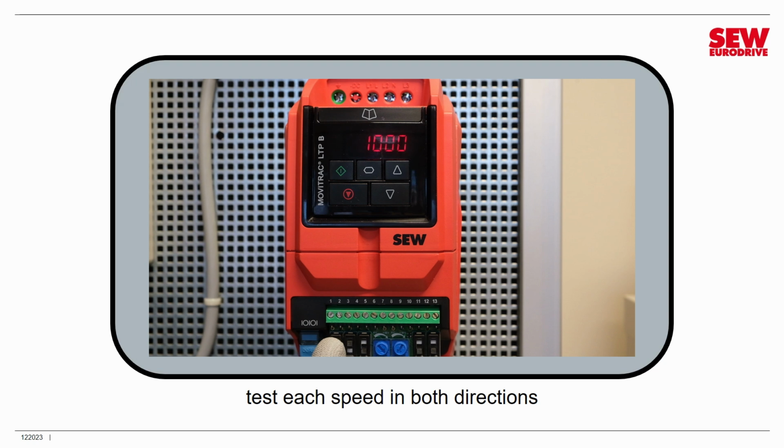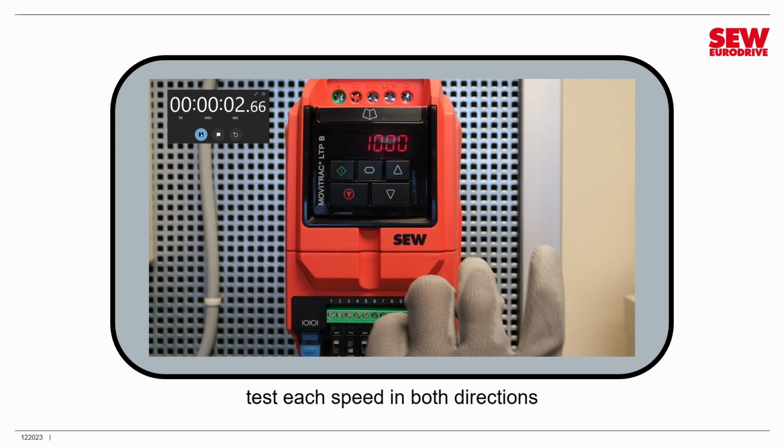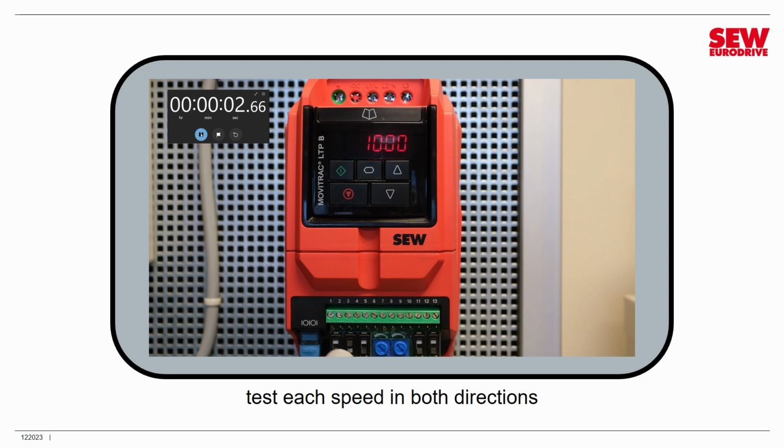So we're going to trigger a stop by turning digital input 1 off. And you can see there's our relatively slow ramp. Turn it back on. And now we're going to engage the fast ramp. So we'll turn digital input 5 all the way up there. And we'll trigger it by turning digital input 1 off. And you can see that happen twice as fast, which is what it's supposed to do. So there we go. Everything works.